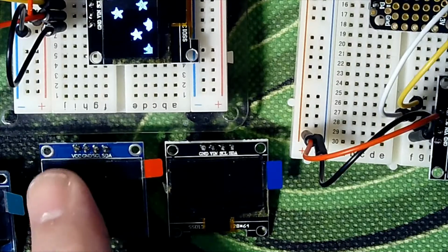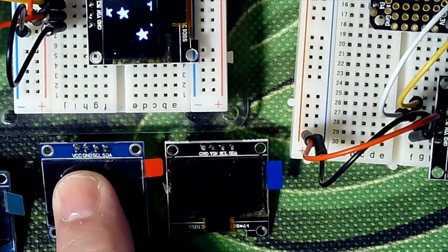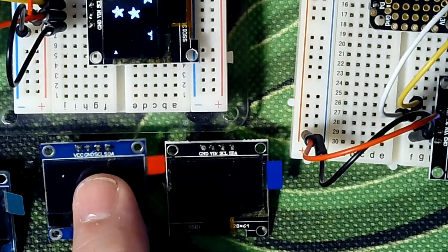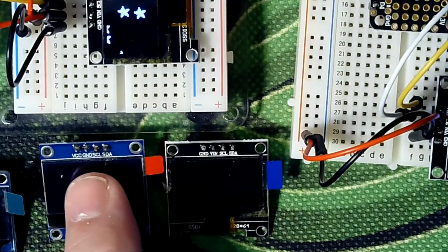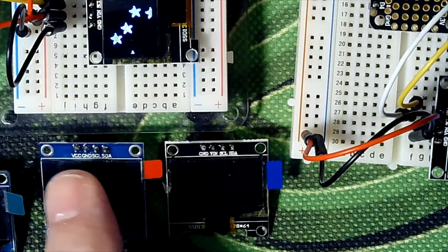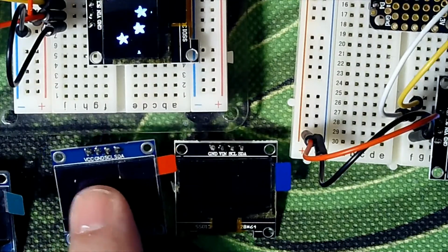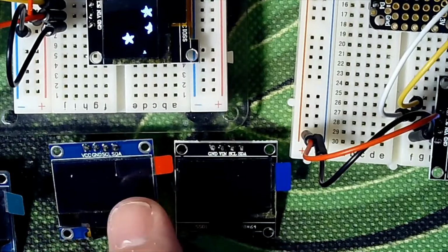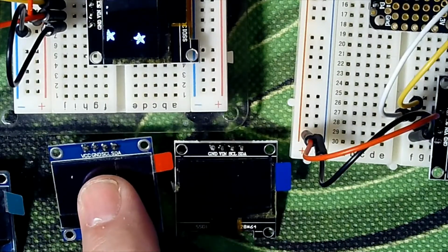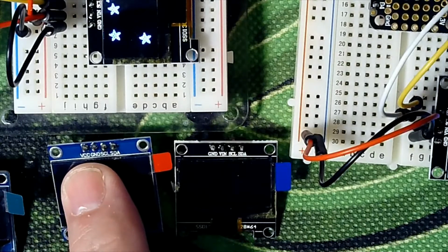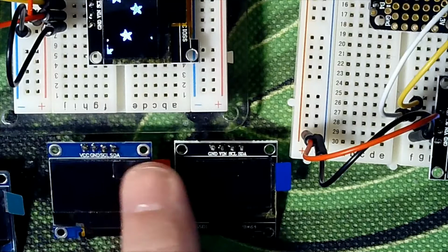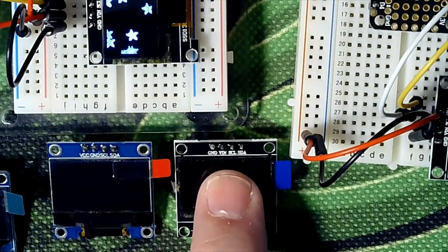Compare it to this one. This one starts with VCC, so that's your power, then your ground, then your SCL and SDA. So the ground and the power pin, this one 5 volt, again, it usually works on 3 volt as well. Most OLEDs will work on both. You find that these 2 pins are reversed. They actually put positive on the outside edge and they put ground on the inside edge, but the 2 communication lines are still the same.